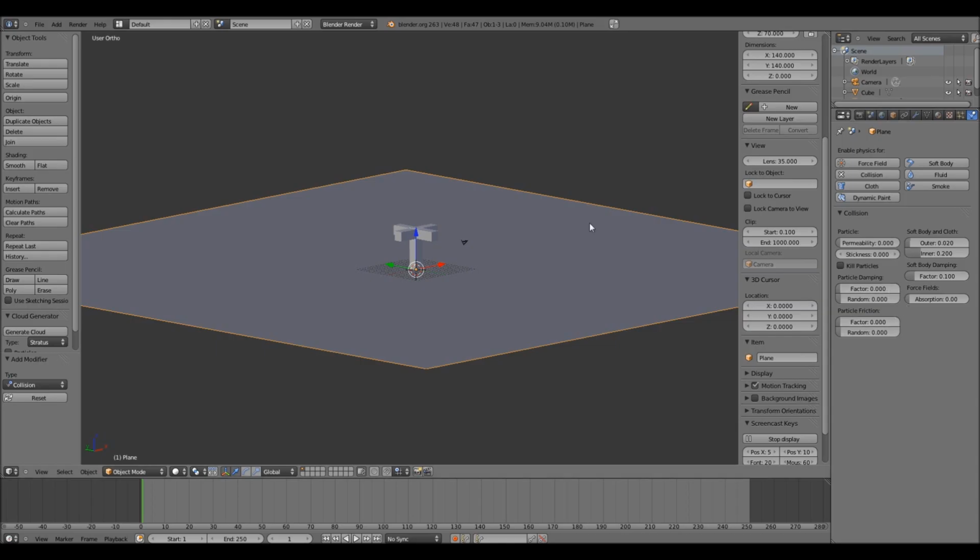So if damping is set to 0, the particles will hit the floor and jump off with the same amount of energy they were emitted with. If the damping is set to 1, particles would hit the floor and stay there because they would give away all the energy. Or in other words, the object would consume or absorb the entire energy of the particle.